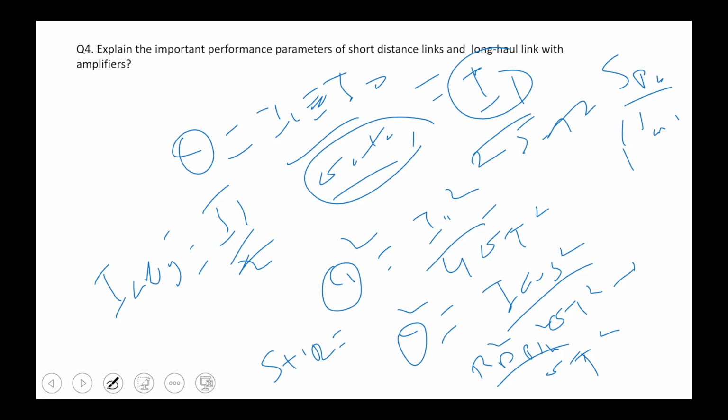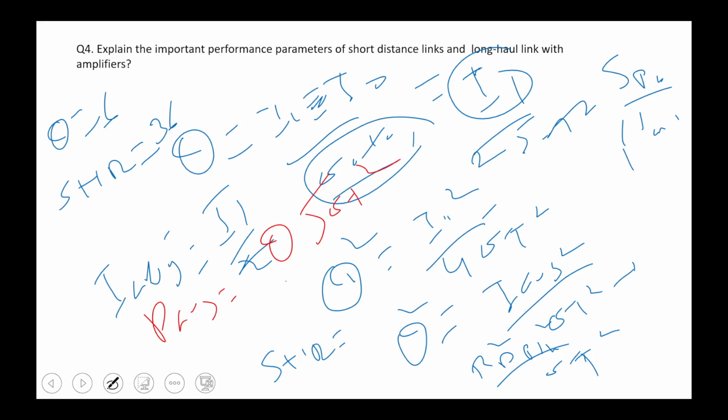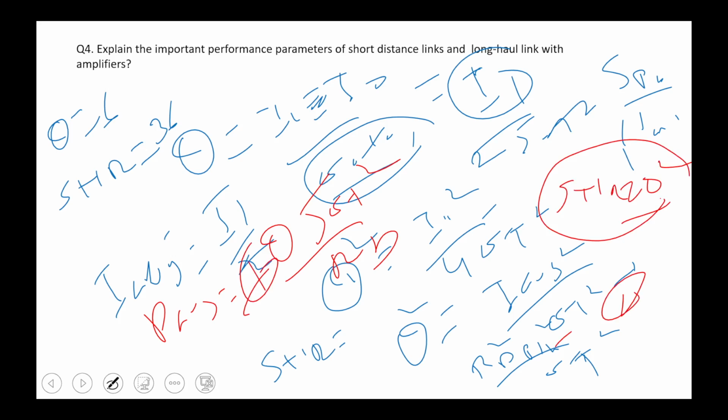If we suppose that our signal has a quality factor equal to 6, then SNR is equal to 36. Some important things to calculate: we have to take care of the thermal noise in this case. For receiver sensitivity, I already explained that P average in case of thermal noise equals Q times sigma t upon the responsivity R. So from this equation and this equation we calculate SNR equal to Q square. It's a given relation that SNR equals Q square.